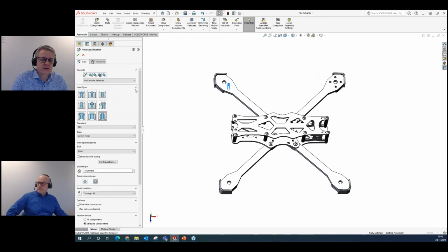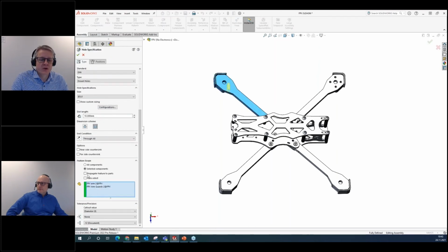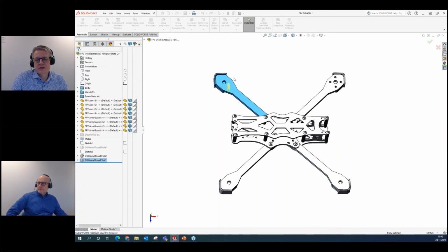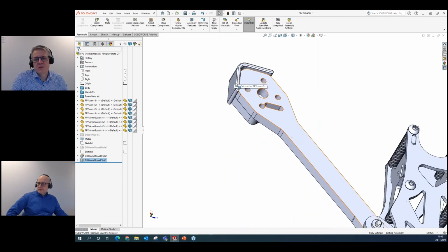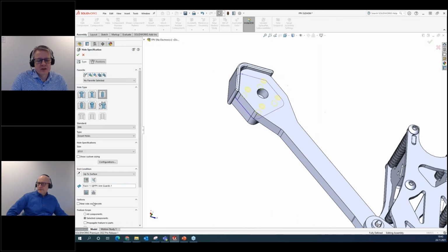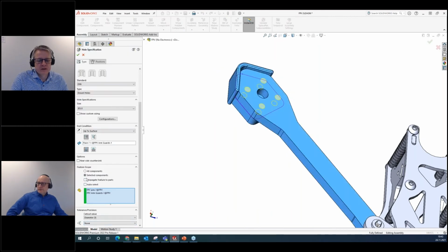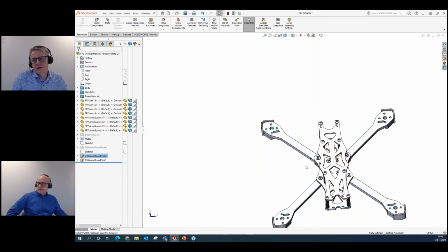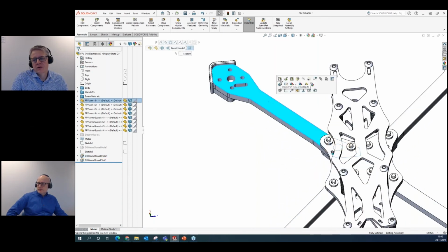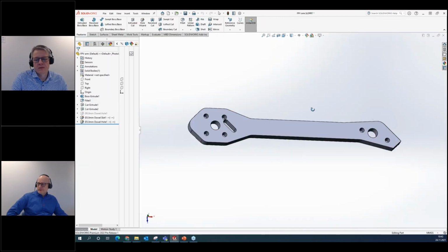go into edit and I add the check mark for propagate featured part. Then this slot will be added to the pattern and all the way down to the part level. And I can do the same with this existing hole pattern. I can edit, I can check the propagate featured part, OK. And we will now see that everything goes down and also on the part level.